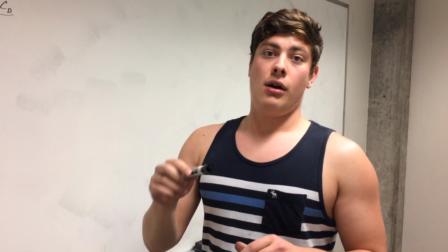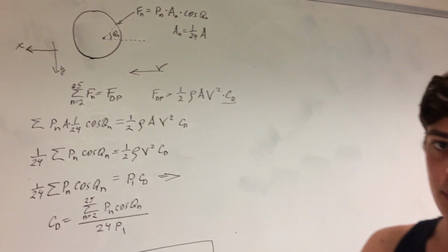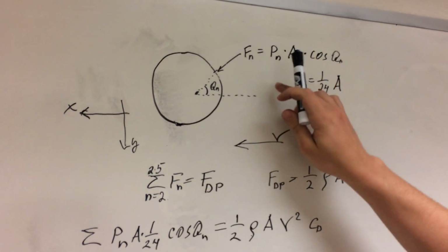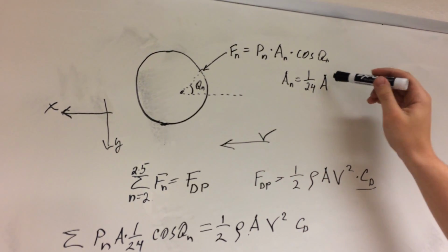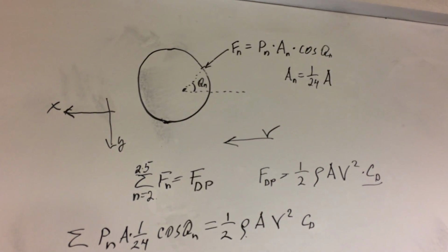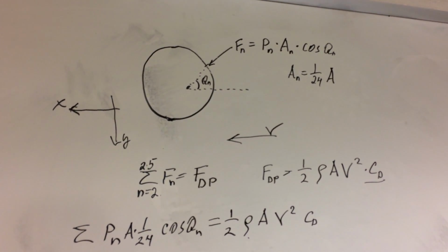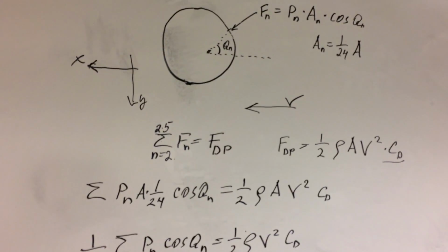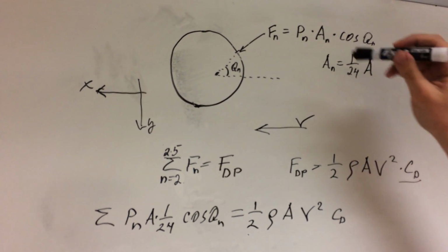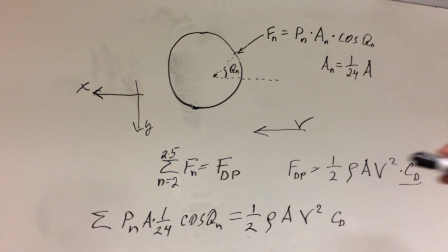The total force due to pressure drag on the cylinder is an integral of pressure around the cylinder over the surface area of the cylinder. We can approximate the total integral by summing pressure readings multiplied by the area of the panel. Since we only got 24 pressure readings, we will assume that the cylinder is a 24-gon, and each area around the pressure tap is 1/24 of the total area of the cylinder.